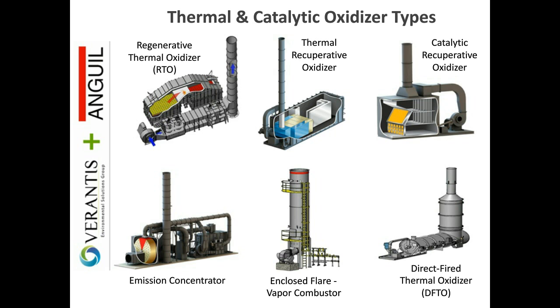This slide, so now we're getting into the actual technical slides here on the oxidizer portion. So this slide covers all the technologies that I'll be talking about. And essentially, this covers all the oxidizer technologies that are out there. There are subsets of each of these that you could have individually mentioned, but for the most part, this covers them all, and I'll touch on each one of them. The majority of my time, though, will be spent on the technology in the upper left-hand corner, the regenerative thermal oxidizer, or the RTO, as it's referred to. The reason I'll spend the majority of my time talking about that is that it is by far the number one technology right now in terms of oxidizers.